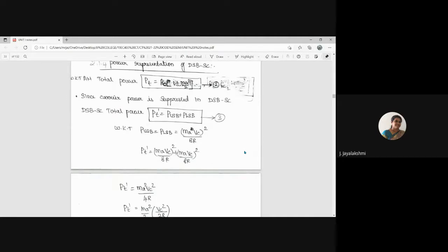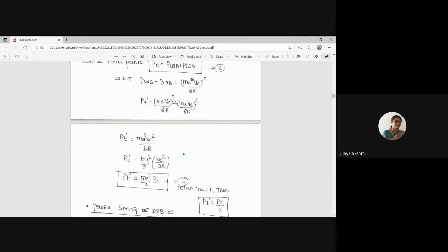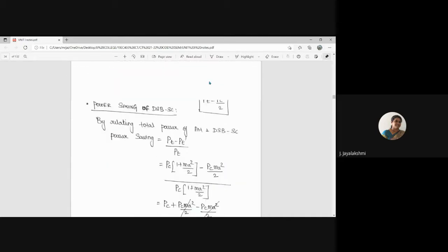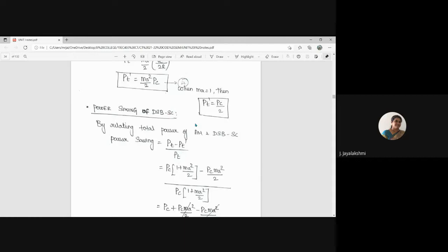We were discussing the power efficiency of the different AM modulation schemes. Am I right? The power representation for the double sideband suppressed carrier depends only on the sidebands. Carrier is suppressed, so no need to calculate the power carried by the carrier. You are bothered about the power carried by the sidebands.